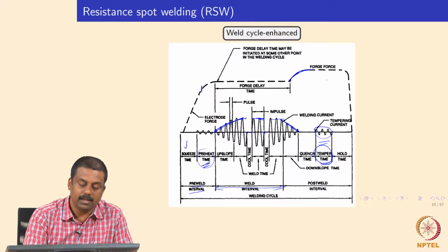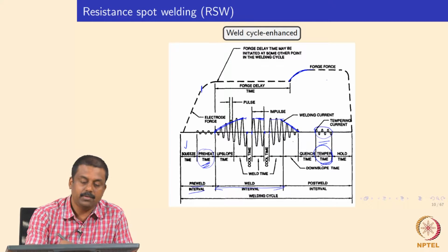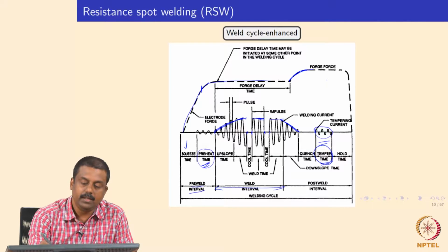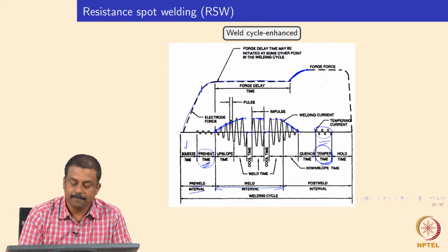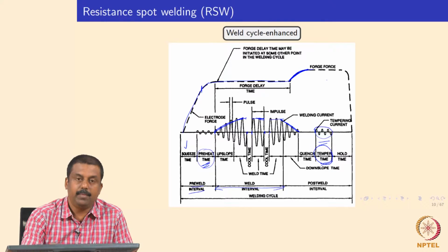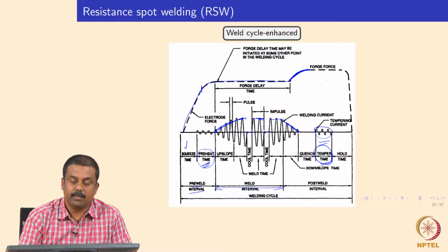You can also preheat by applying some short pulsing before the actual welding current, and you can change the loads based on our need. In this typical cycle, we also have an increasing load when the weld nugget is cooled, to mitigate the residual stress. All of them can be used in our favor to modify the weld thermal cycle.